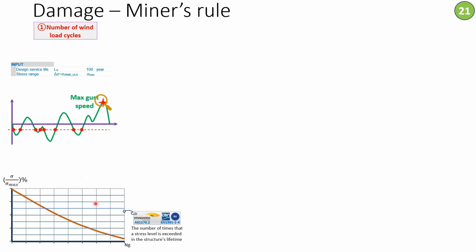So how do we use this segmentation or stress increments to calculate the damage? We will study one segment and understand the process on that one segment, and that should be repeated for all stress segments shown here. If we take, for example, this stress segment, it represents a stress increment, and it intersects with the graph at two points, this point and this point.